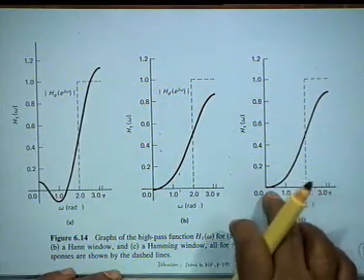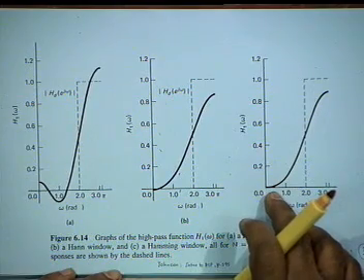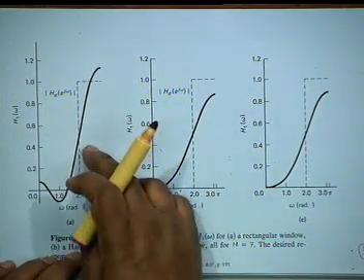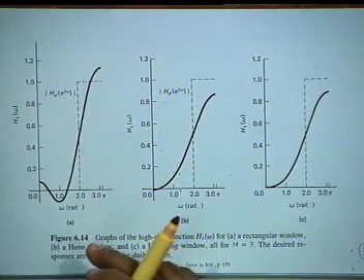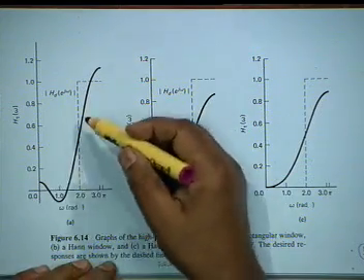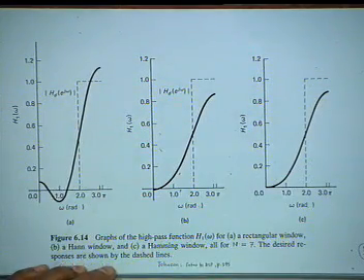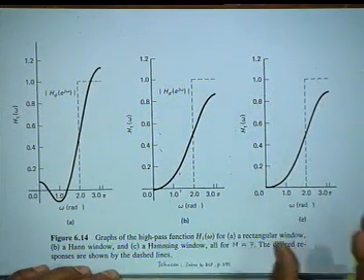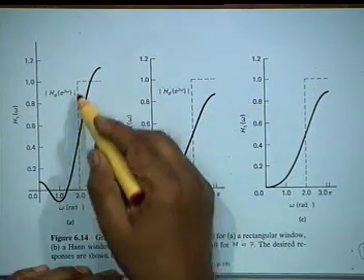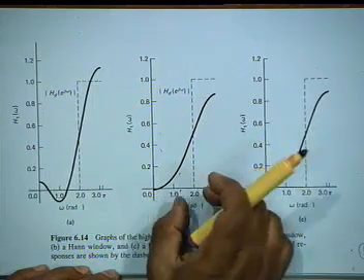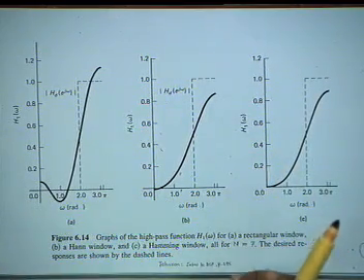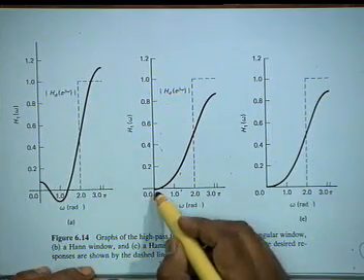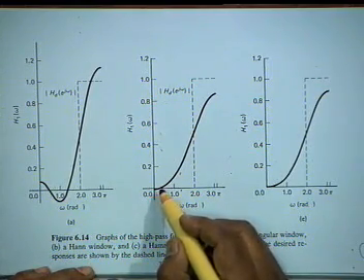You see, the undershoot here is almost unnoticeable, okay? But the main lobe width, in other words the cutoff, sharpness of cutoff, now it would be the slope would be positive now because it is a high pass filter, okay? And you see that this slope deteriorates with Hann and Hamming. Slope deteriorates means this is the ideal response, okay? Means this gap, no, which gap? The zero crossing, no, not even that. There is a ripple here, there is hardly a ripple here, there is a small undershoot, okay?